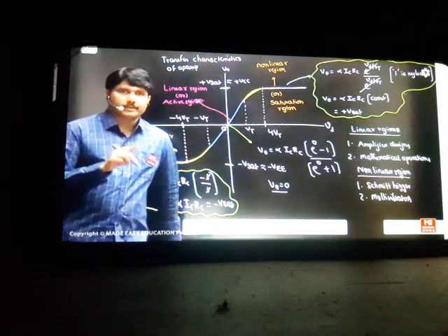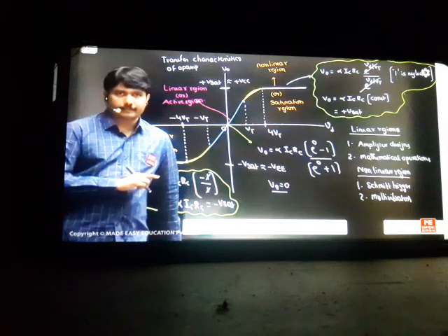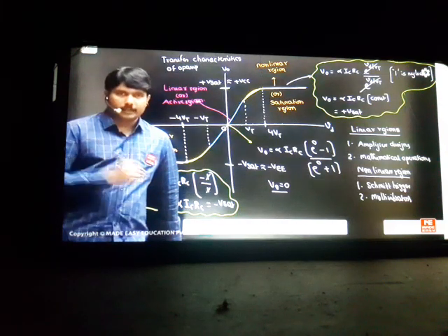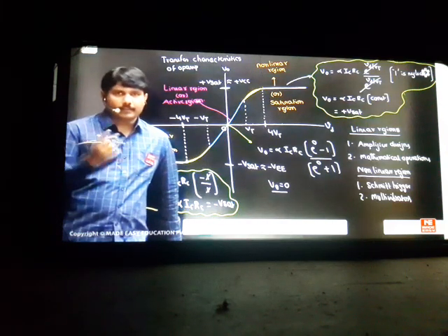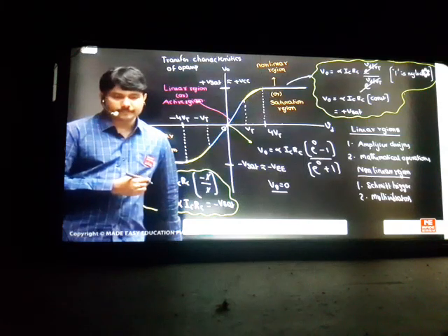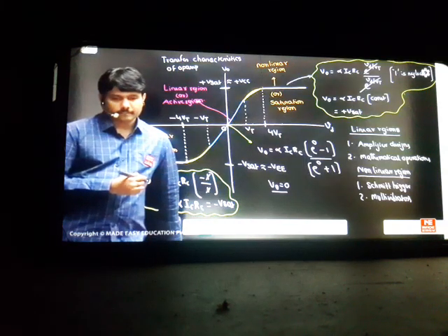One situation is there. Open-loop op-amp, if it was supposed to be in non-linear, it cannot work in linear. If positive feedback is telling I work in non-linear, it cannot work in linear. Negative feedback is telling I work in linear, I cannot work in non-linear. All these cases we have to understand now beautifully. Okay, the conclusion of each topic we will also understand.